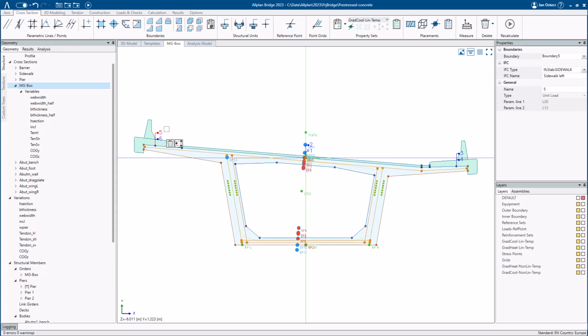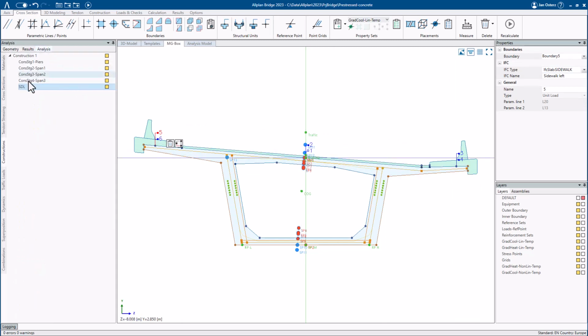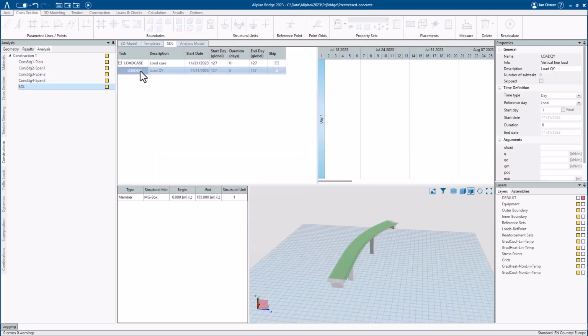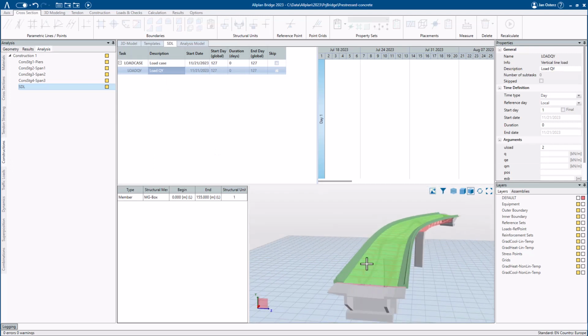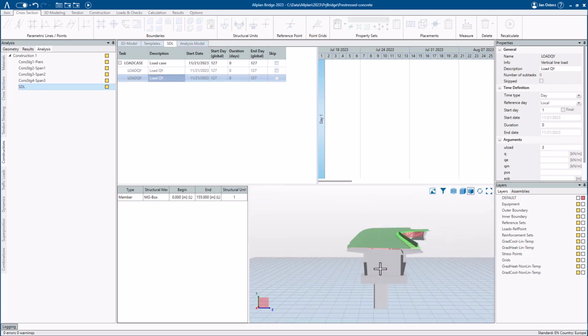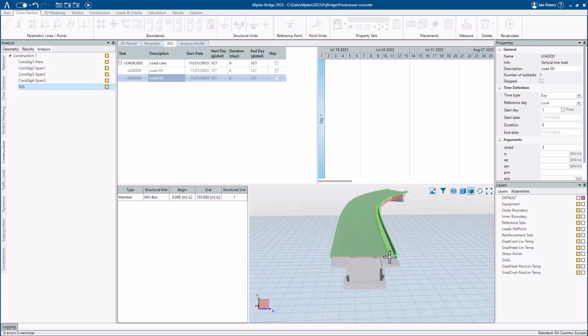So for example, we have 5 and 6, 3 and 4, and the number 2 for the roadway. So just so that you know where I'm getting these numbers from, but you will see just in a moment, once I type in the number 2, this is now confirmed. And if I click back again, I see this highlighted in a green color, so this means that this roadway is being activated here. So I will just copy this one with assemblies and continue with the right sidewalk. So number 3. And if I switch, you see now only this right sidewalk is being activated here.